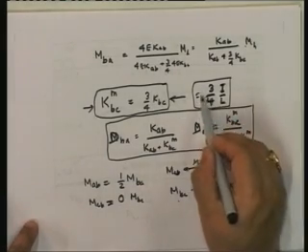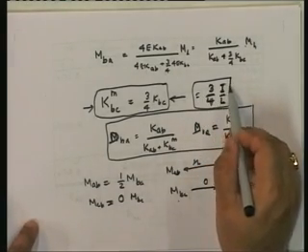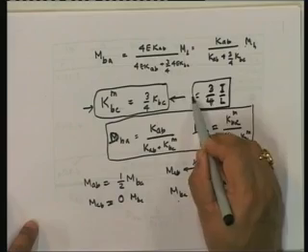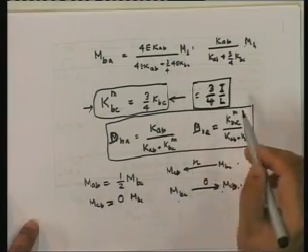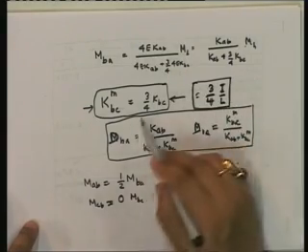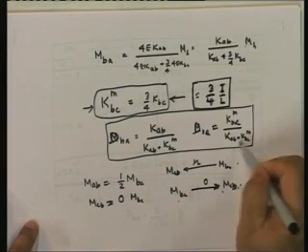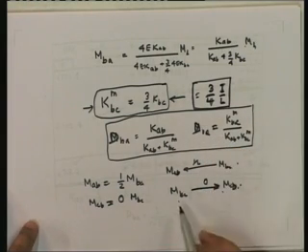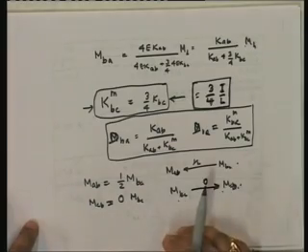So all you have to do is, for the modified member, at the continuous end, you just make the stiffness 3/4, and so the distribution uses the modified stiffness in the distribution factor computation, and secondly, there is no carryover in a modified member ever. Okay? So this, in essence, is the application of the modified element in the moment distribution method.